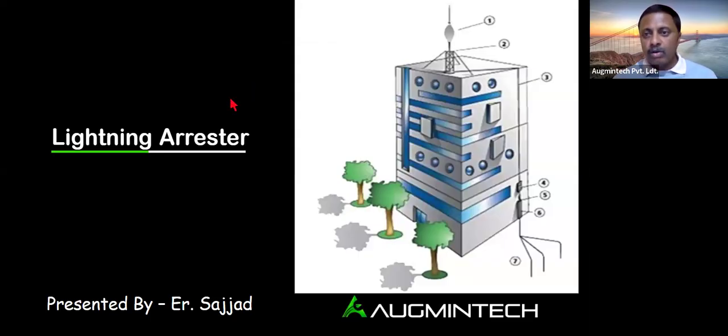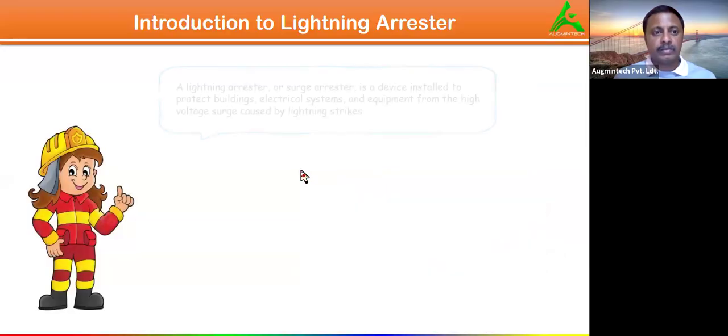So, what are the components that would be in a lightning arrestor system? As you're saying, in this building, there's going to be an air rod or a lightning rod, we say, and then this should be connected to a down conductor, and finally towards an earth pit, right? So these are only the three components of our lightning protection system. Fine. So let's enter into the basics.